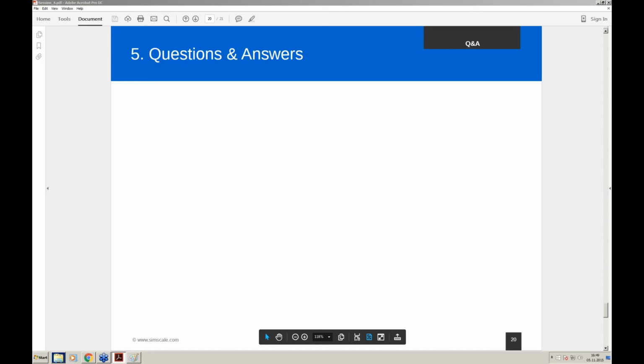Yes, it's basically possible. So if I got your question right, you want to work on one simulation, let's say a flow simulation, and you have a mesh and the setup prepared, and you now want to set up the second simulation while the first one is running, right? That's possible. So at the moment where you click here, create a new run, you are creating a new snapshot and you can edit the rest of your simulation. Great. Are there more questions?